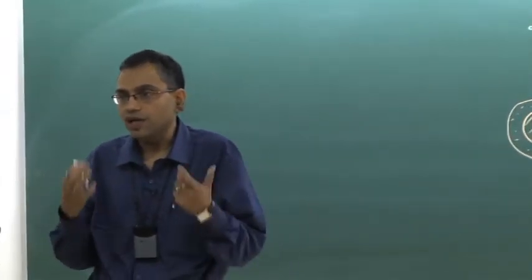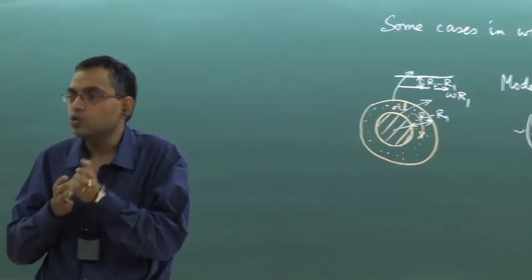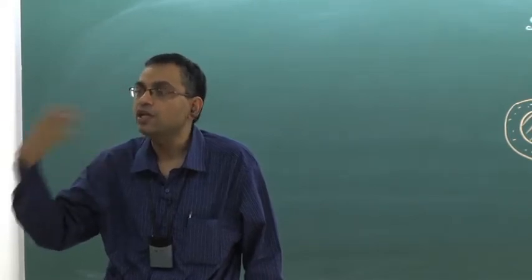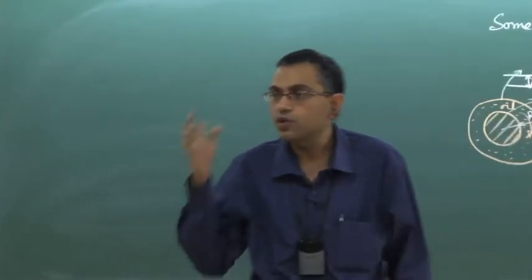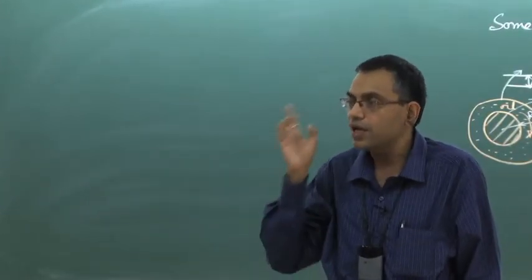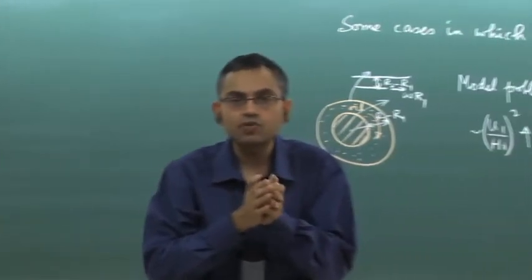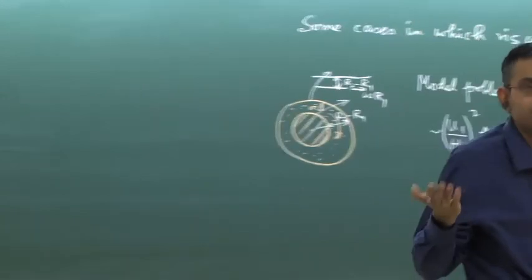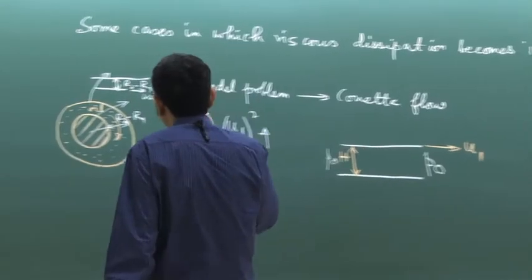It will convert the work done due to shear between various fluid layers irreversibly into intermolecular energy, or internal energy, that will raise the temperature. We have shown during our derivations that it will trivially raise the temperature. It is trivially heating and not cooling. Just like if you rub your palms, you do not expect that your palms will get cooler, right, you expect that they will become hotter. The same mechanism works here, and when it becomes hotter, that will act like a heat source in this oil.